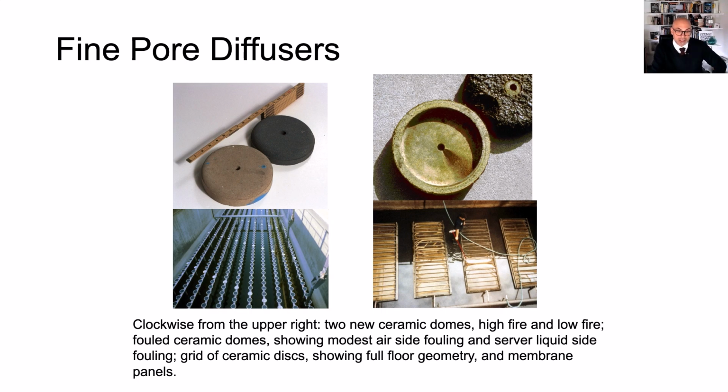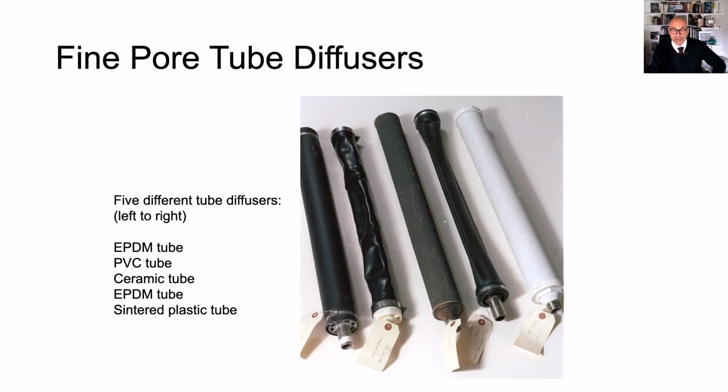Cleaning is necessary, especially for panels, because they're on the floor, and otherwise grit most likely will damage them. So that's another issue that we need to remember, to always remove grit before any aeration system. That's another issue that really plagues aeration systems.